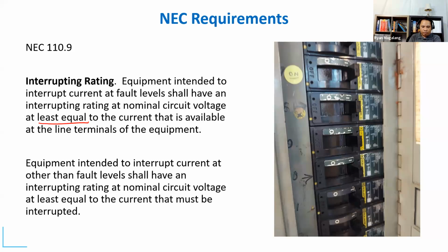And it's one of the objectives that I mentioned earlier, that the devices, your panel boards, let's say, and your breakers should be capable of interrupting the fault level at that point.